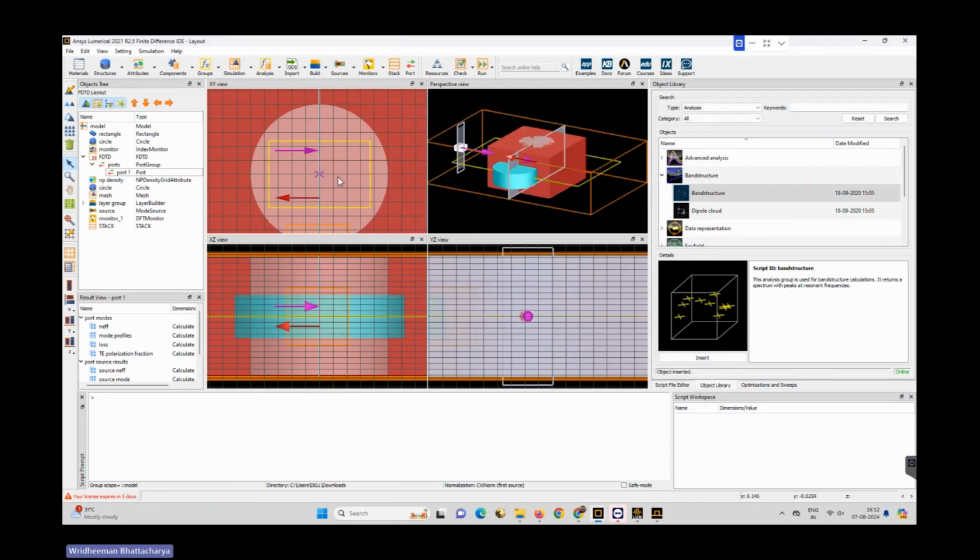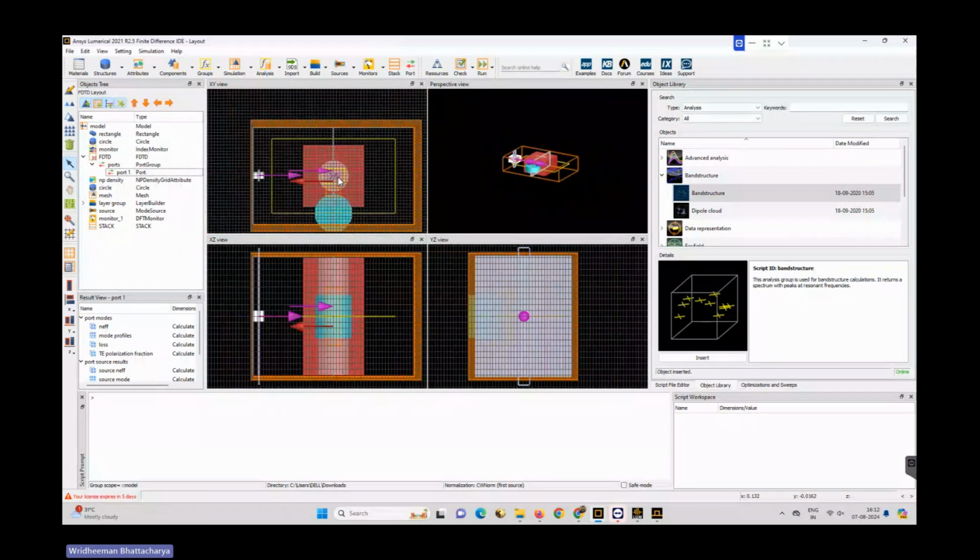So now I will mention one thing. Whenever one is starting a simulation, one should do a convergence testing. So what is the role of convergence testing? If the system is not stable, it might give you different results for different simulations, right? So we have to first stabilize our whole environment. So how to stabilize that whole environment?